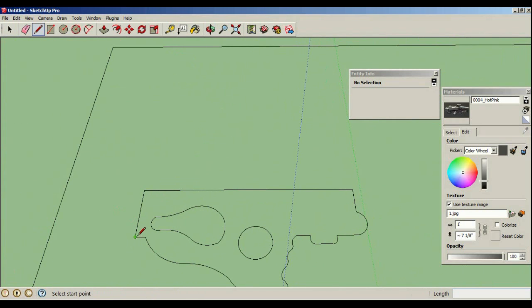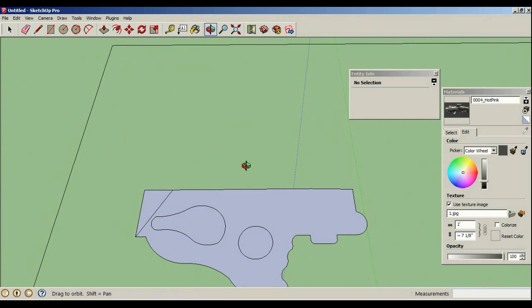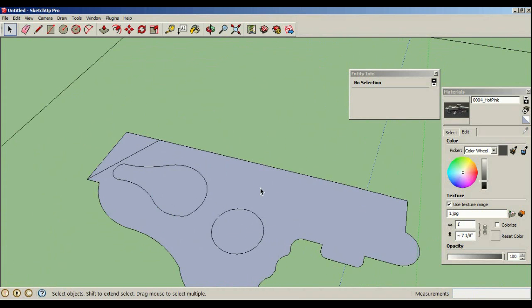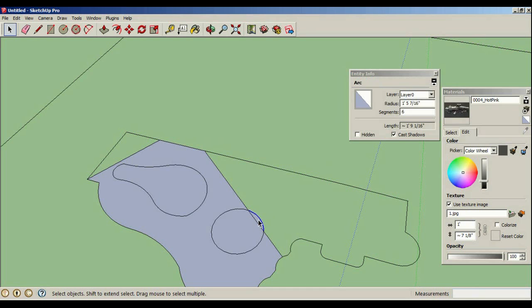And in case you don't have a, what would you say, plane, you can do this. Just draw a line across and hopefully fill in the plane, which works sometimes. It's being a bit finicky because there is some edge that is not 100% closed.